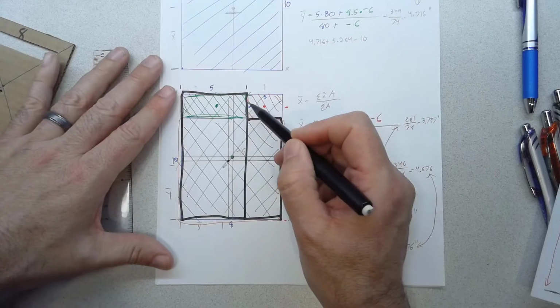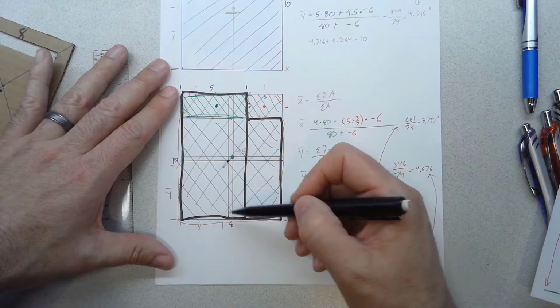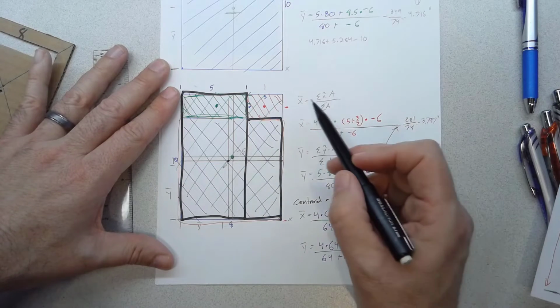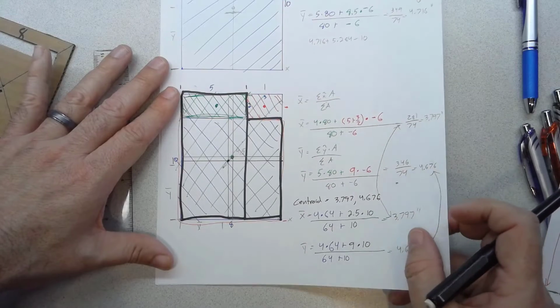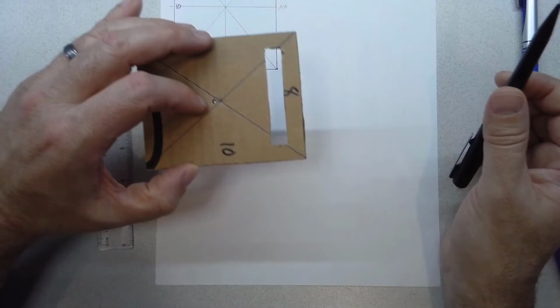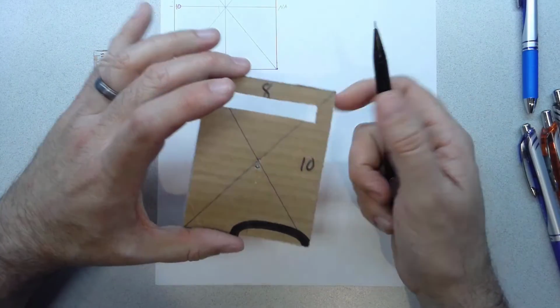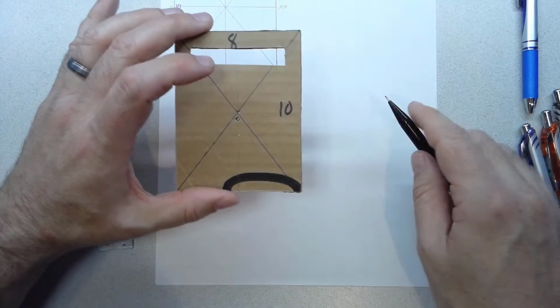And once we did that, just as a reminder, now we have no symmetry. We don't have symmetry about x or y, so then we have to find the distance to the centroid in both x and y. So just a reminder, that's what centroids are about. And centroid is an easy to visualize thing, because you can empirically find the centroid of an object by just figuring out where it balances, right?